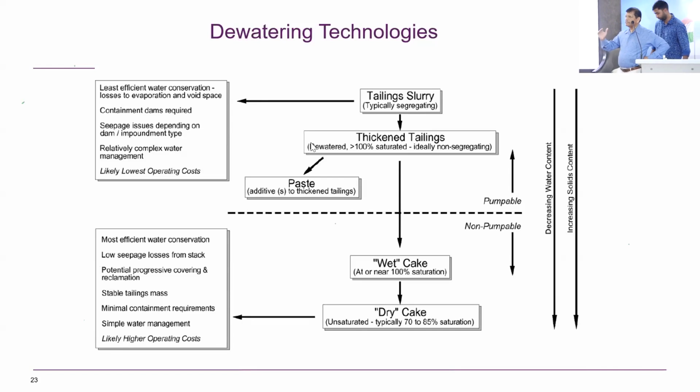Whether it stays above depends on the pore pressure, because as pore pressure is increasing, strength is decreasing. So we monitor the pore pressure. I mentioned we have all these piezometers. Every piezometer has a threshold value, and that threshold value is normally 5 feet or 10 feet below the failure pore pressure.